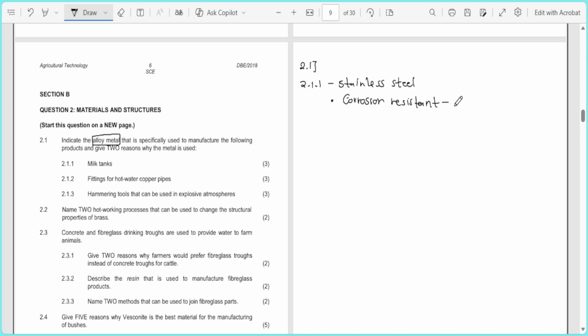So using stainless steel is a better option, because the chromium it contains forms a passive oxide layer that prevents rust and chemical attacks that come from the chemical sterilizers. So the reason we are opting for stainless steel is its corrosion resistance.